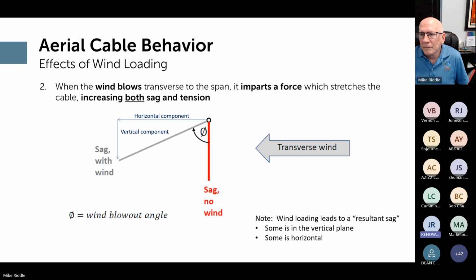But if you've got a 500 or 1,000 foot rolling span line, that dynamometer could be a source of errors, depending on where it is, if it's been calibrated, is it digital or mechanical?